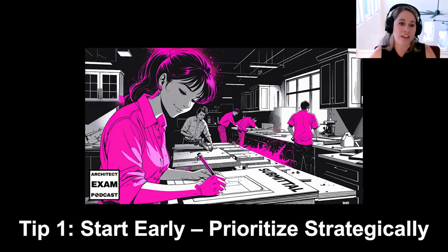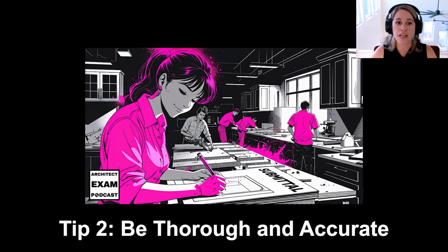And make sure, again, that you prioritize the larger submittals so that it doesn't affect multiple trades. If you need to prioritize, again, windows and doors or maybe conveying systems, because other trades that are connected to those components need to have their items in place as well, and they shouldn't be delayed if the other items are not installed first.